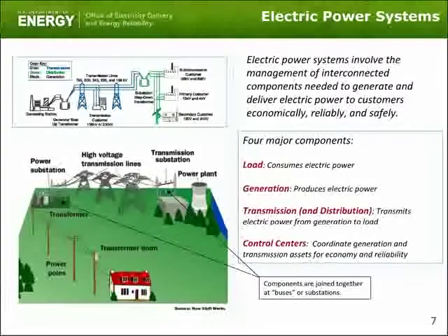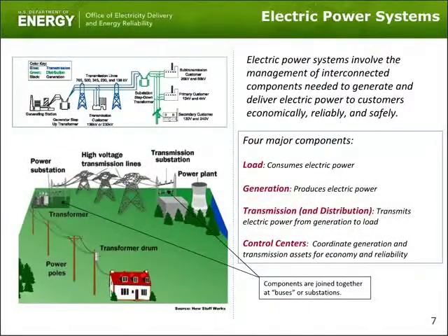As shown on the diagrams on the left, much of the current electric grid was designed and built using technologies and organizational principles developed decades ago to serve large-scale generation sources remotely located from consumers, to accommodate one-way flow of power, and centralized control schemes with minimal feedback. There are 4 major components, and they're laid out on the right-hand side: load, generation, transmission, and substations, which help join the system together.